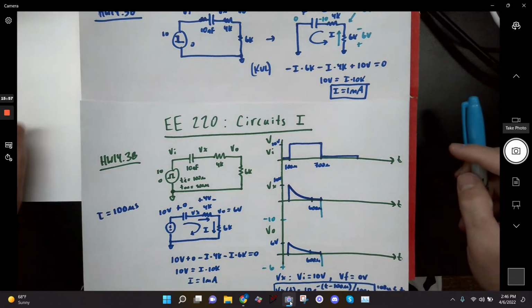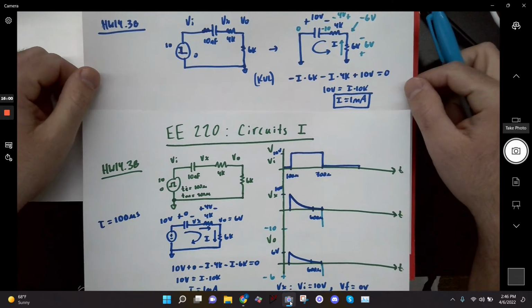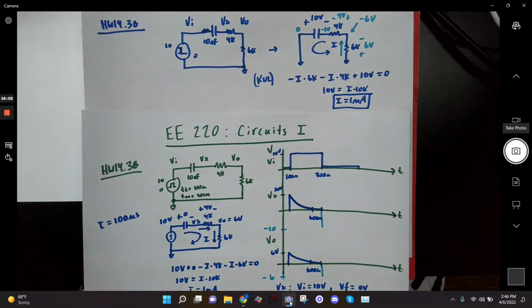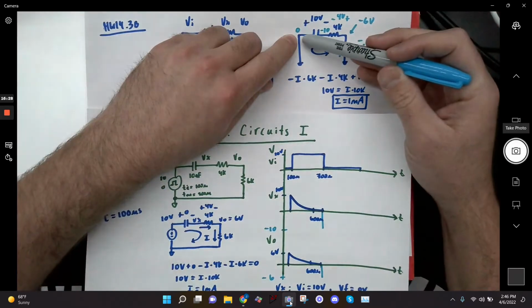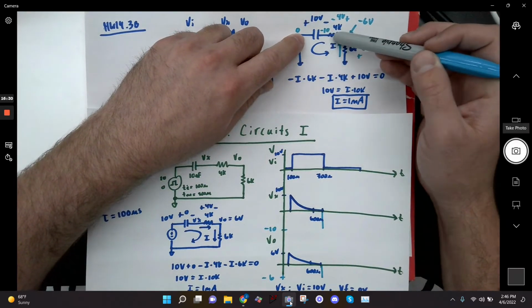Because we talked about, like in class just Monday, the reason why it flips to negative is because you have to maintain that potential difference. So we know there's a potential difference over that capacitor of 10 volts, but because it's 0 volts, it has to go to negative 10 volts to maintain that difference. So I just rationalized that that's what was going on, and then found my drops the opposite way. Yeah, that works. That works because I imagine what you're saying is you knew this was 0, you knew you needed 10 volts across it, so you knew this went to negative 10.